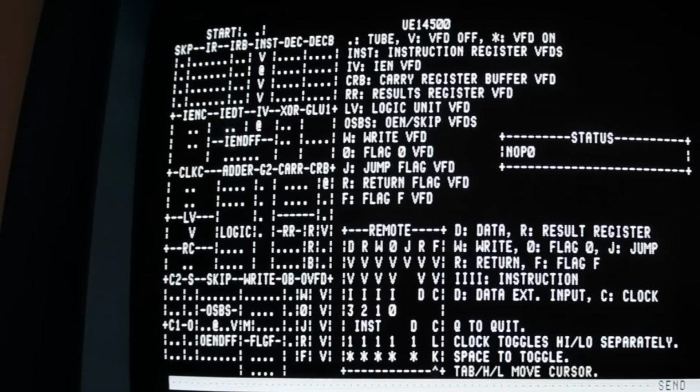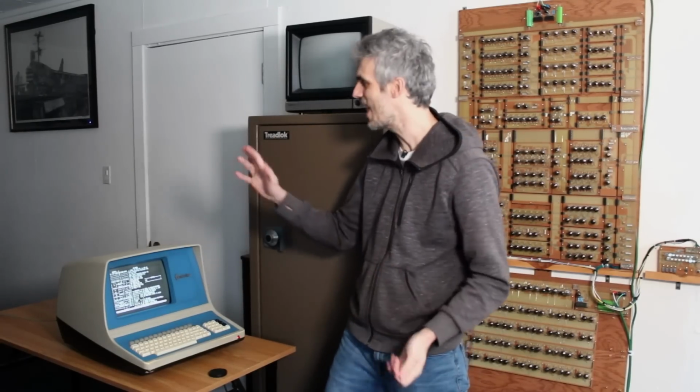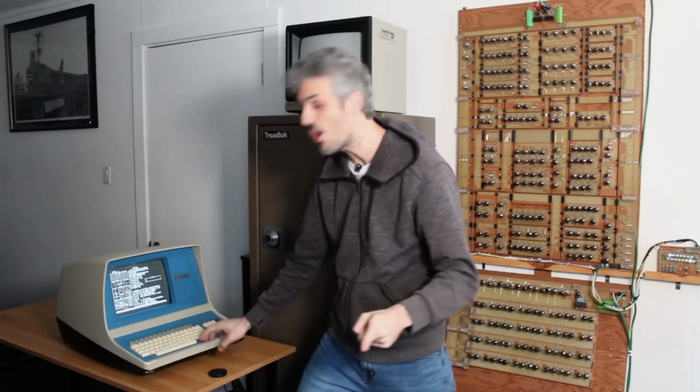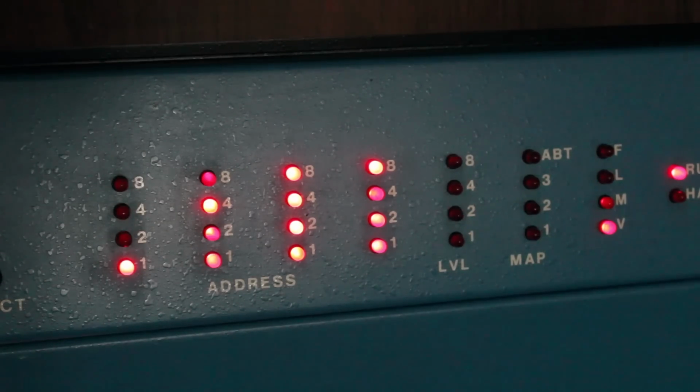So we'll just do a simple operation here. We'll load a 1 into the result register. That's going to mark a change. So when I hit the clock here, the blinking lights flash. They do something. So there's some calculation going on, and it lasts, I don't know, about half a second to a second. And then on the falling edge, when I turn the clock off here, looking at the blinking lights, they go for like 1/10 of the time.